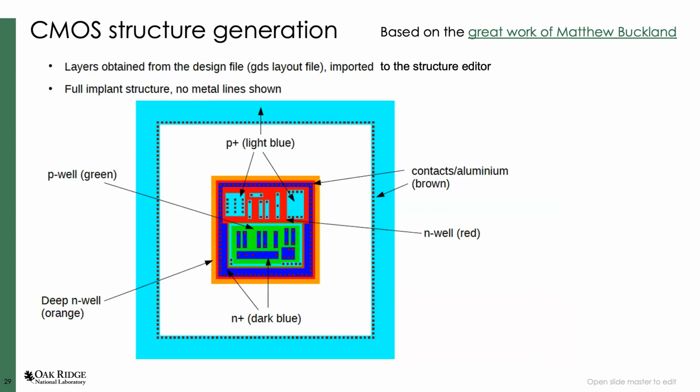Another way to do structure generation, and I just have a few examples there as well. You can also take things that come from design. In that case, there was another design that was done in AMS, an HV CMOS process. It was a very small pixel. In the center area, this is where you apply the high voltage, so we call it the P sub, the substrate contacts. And in the middle here was the pixel, the big N well, and inside there is the P well and the N well, and then the transistors that are inside that device.